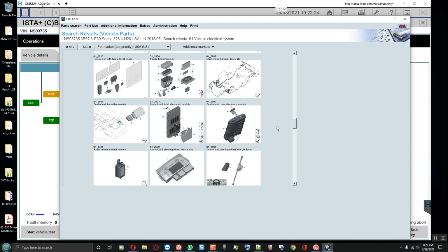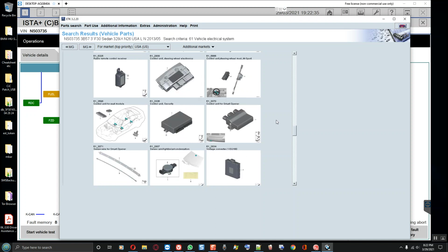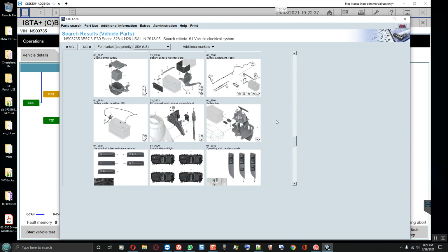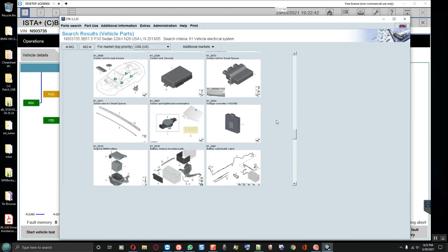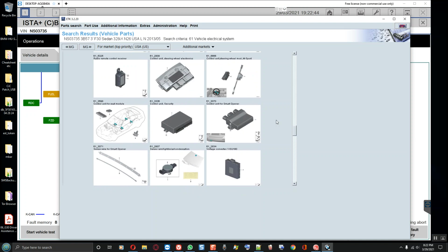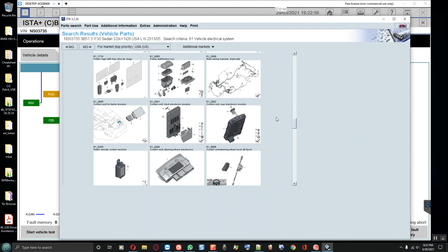We can't bet anytime I'm right on that. They're gonna come up with different part numbers for the equipment for the ICM. Well, the sensor it's looking for only has to do with the airbag. It wouldn't have anything to do with the LED light, so you wouldn't have to put a new ICM in. All right. If you're right on that, that means you have to pay attention to the open circuit then. That has to be solved, because we're gonna always be in a spin cycle of guessing, and we do not run a real test. You have to run a real test to find out if the wiring integrity is there.